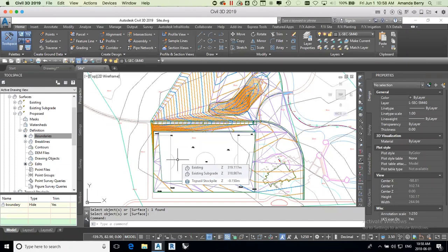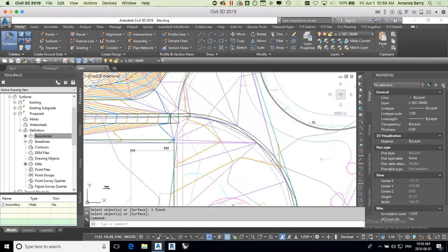And yeah, you should just use Civil to get accurate cut and fills, especially on large sites where drawing contours are extremely long, and sites that could undergo a lot of changes or edits, or you really want to get it right. That's really when Civil becomes powerful. In all of the more simple cases though, just having those simple spot elevation and slope tools will really take you a long way and save you time and money.